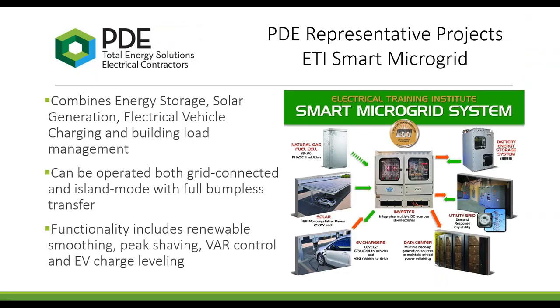This is a microgrid that we did with a Dynapower inverter, a 50 kilowatt microgrid which powered a small data center. You see the 36 kilowatt PV carport array and car charging stations, and part of the project's deliverables were to be able to island in the event of a power outage and keep the data center up and running from a combination of the PV and the battery energy storage.